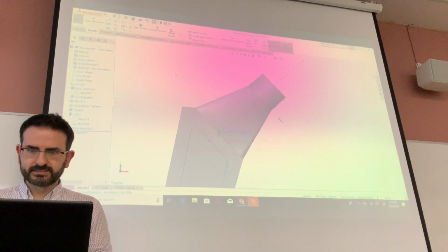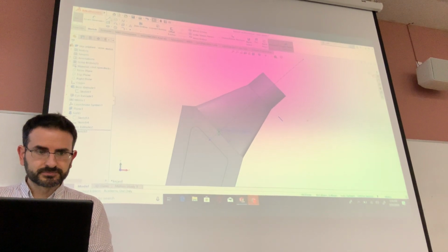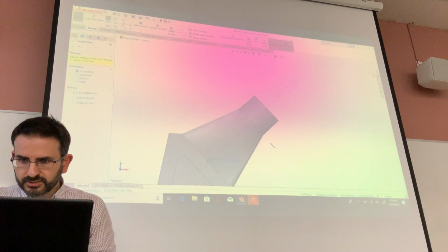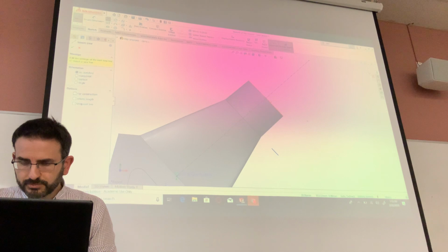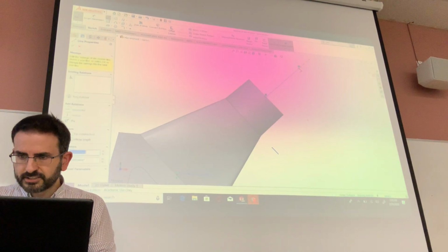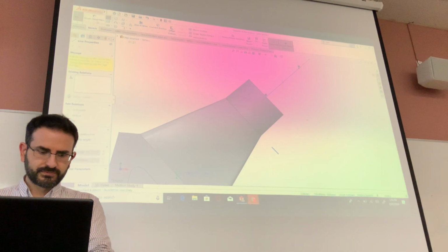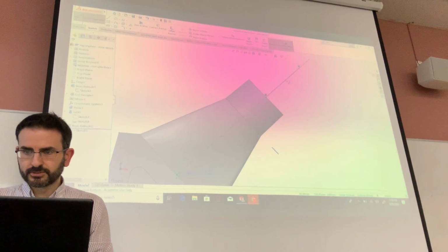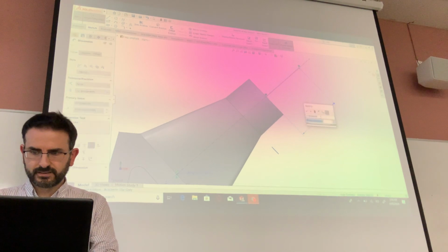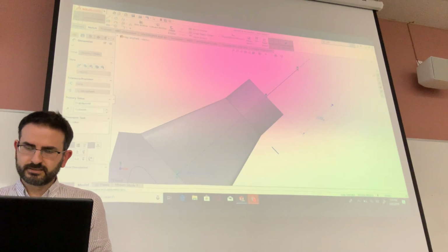And then I'm gonna create that profile sketch. So let's make a line that starts from here. So I need to start from this point here, and let's make it parallel here. And this should be 15. So smart dimension, select, and make it 15. Okay.